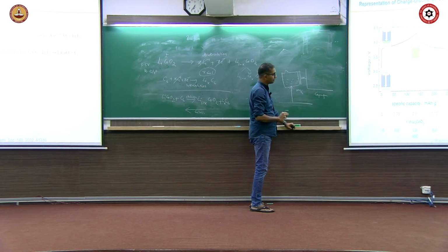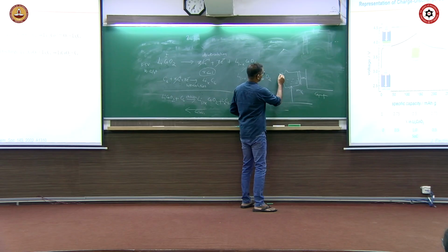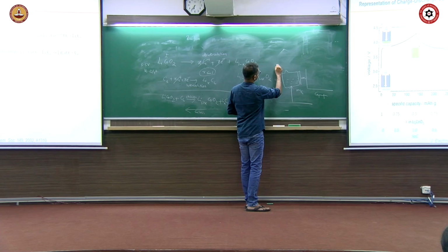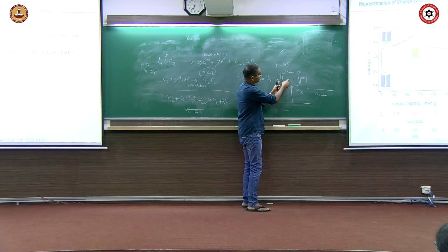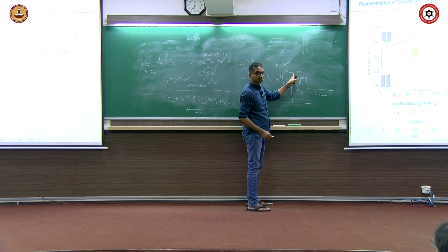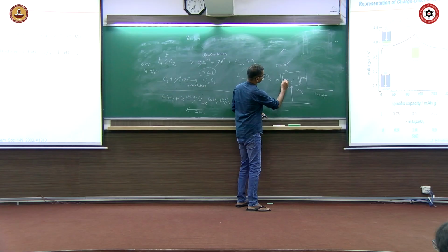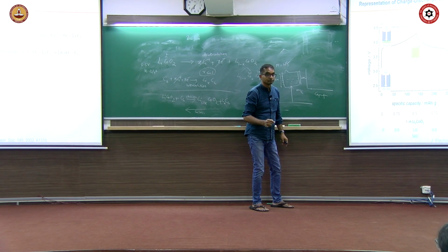Now, let us do it. 1 hour over, how much water would have gone? 100 liters. Suppose, one more thing I will give you. This height is say 10 meters. What is the potential energy? H rho g. Rho will not change, g will not change. Only H will change now. When I put the water in, the height inside will change. Now, I am putting at 100 liters per hour. How many hours will it take to completely fill? 10 hours. So, I divide into 10 portions. So, in 1 hour, how much height would it have gone? 1 meter. So, what is the potential energy?